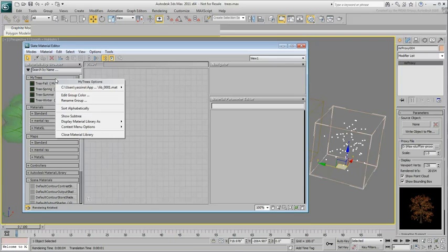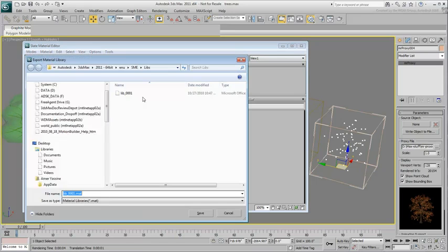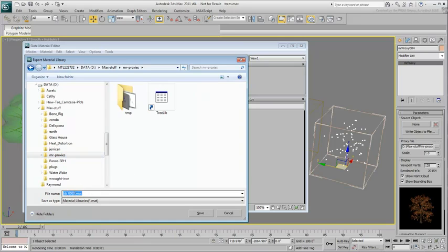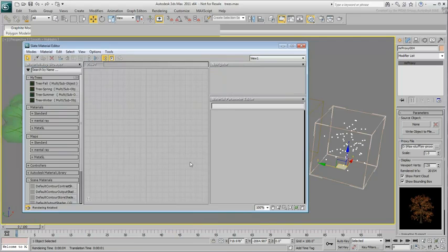Once done, you can now right-click the My Trees rollout and save it as a .mat file and store it to disk, possibly in the same folder as the .mib files. If the materials are using any bitmaps, it is safer to also include the bitmaps into the same folder. In this case, the file named elmleaf.tga that you downloaded along with the scene files is needed for the tree leaves.